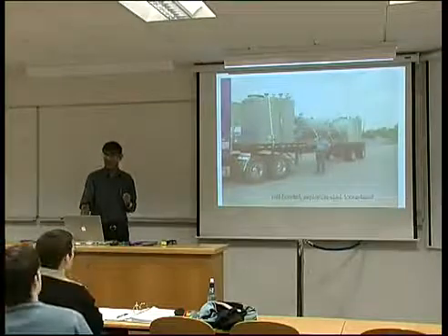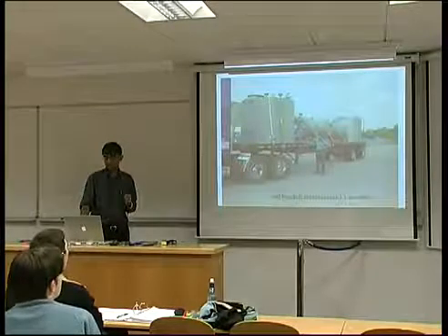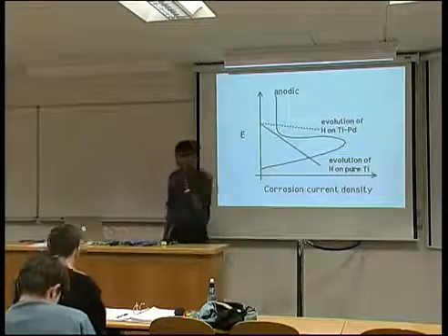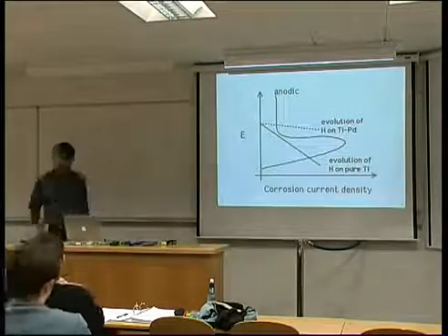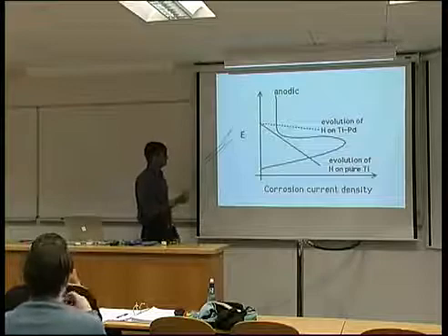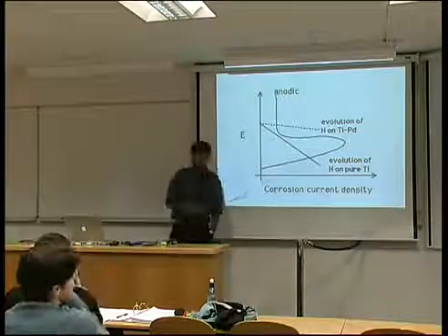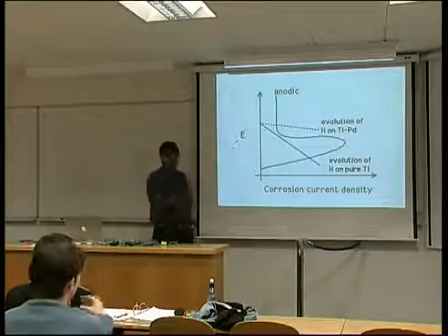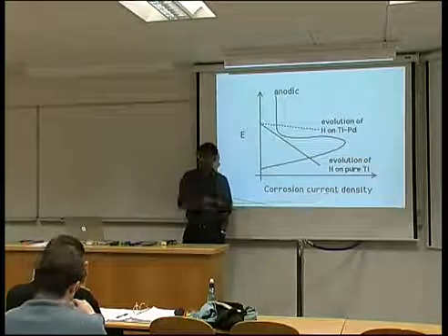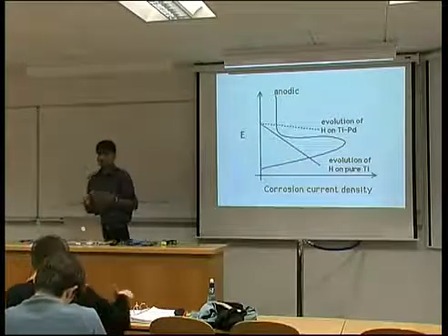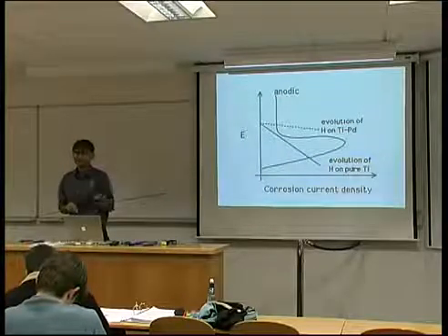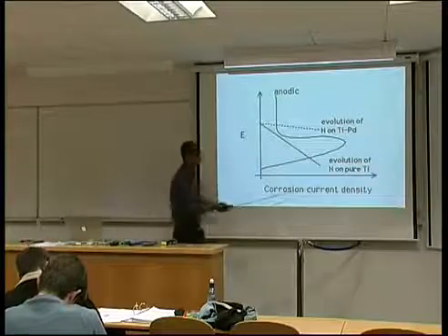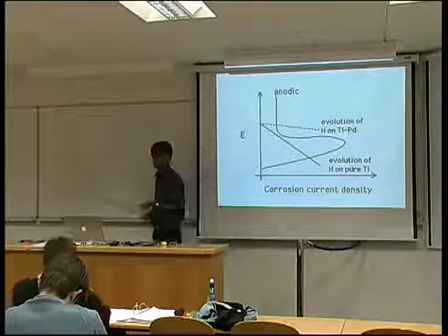Okay, this is another example of chemical plant with explosion clad titanium. Now, let me explain to you why titanium has a good corrosion resistance. This is a plot of the corrosion potential versus the corrosion current density. And you can think about this as a plot of free energy versus the rate of reaction. Because you know that electrochemical potential, if you multiply by ZF, then that becomes the free energy. Yeah? And current density is simply the rate at which a reaction happens. Right?